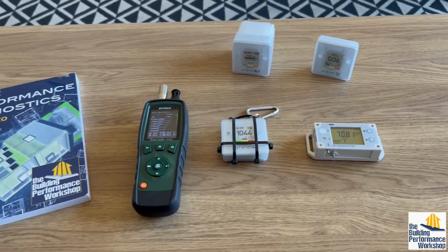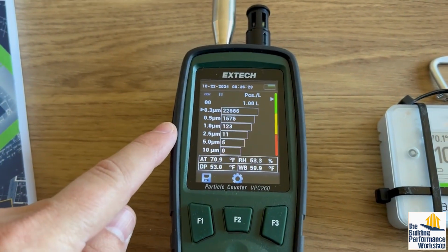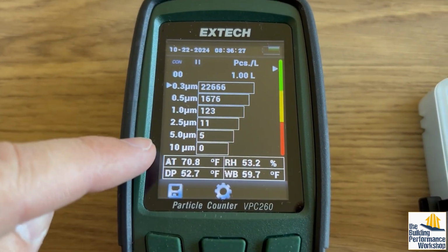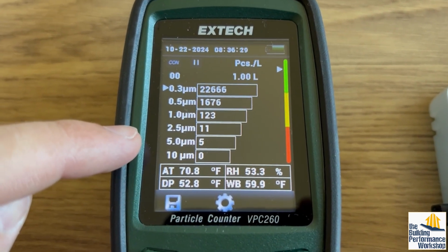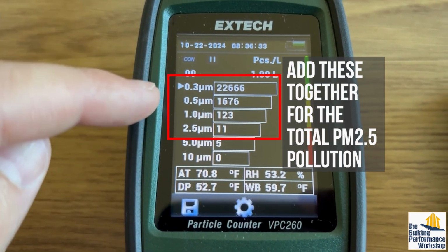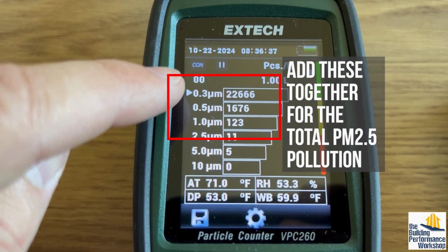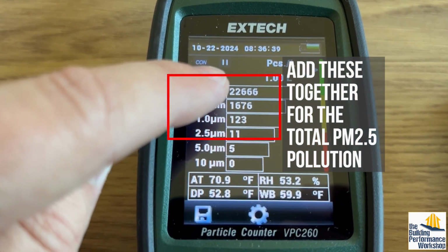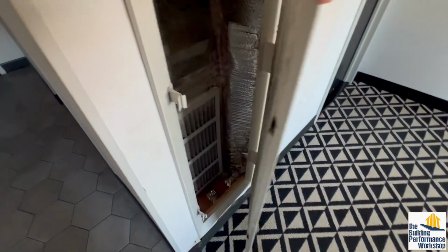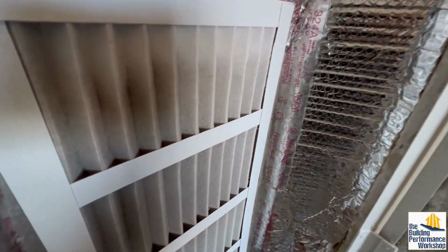And last, contaminants. So I just ran our 6-channel particle counter, and it looks like we're in the green. We have no huge particles. We've got some PM5 particles. We've got a few PM2.5. We've got more 1 micron, 500 nanometer, and 300 nanometer. And this is where a HEPA filter is gonna grab all of those and all of these along with it. So if we had a better filtration system in this room, that would be great. We don't. Deal with it.